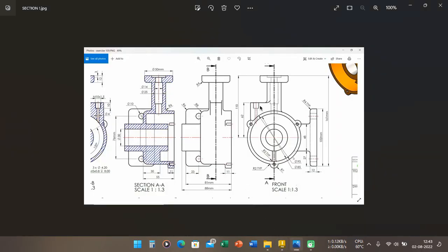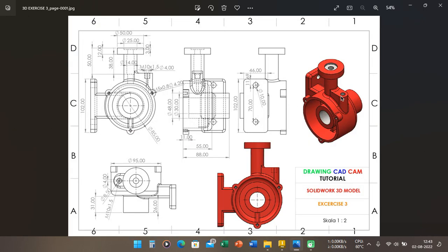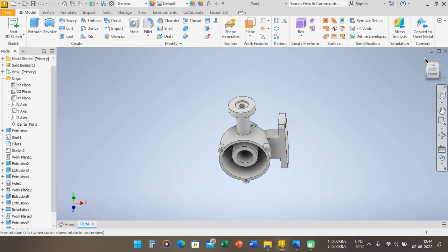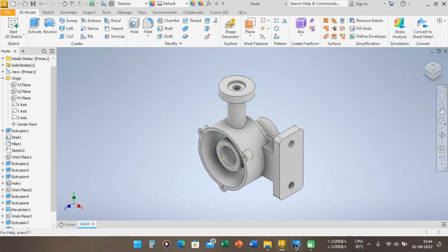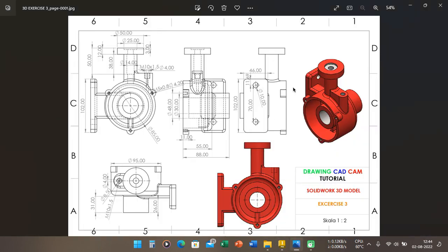After that I want to make the last part here, this, and if we see here again we have the sections within the thread type hole. The thread type hole is M10 multiple 1.5, and the diameter is 40 millimeter, and the tip is up to neck until the inside of this face. So we can make a sketch, and we see here again.